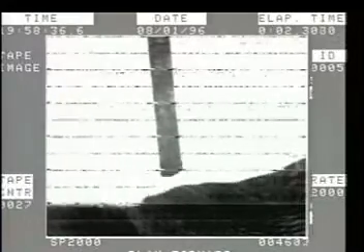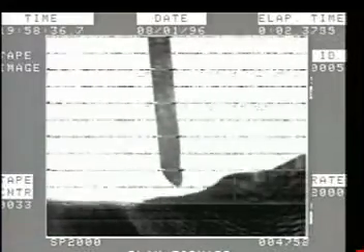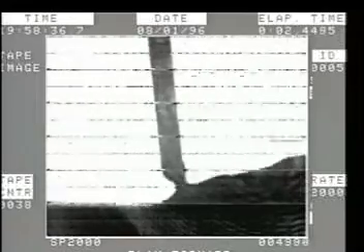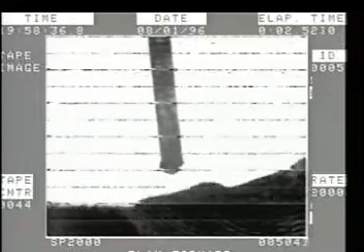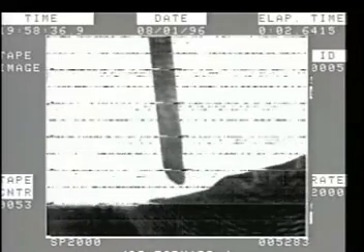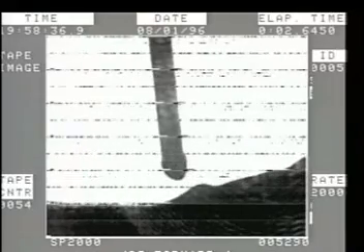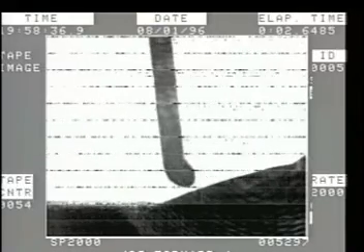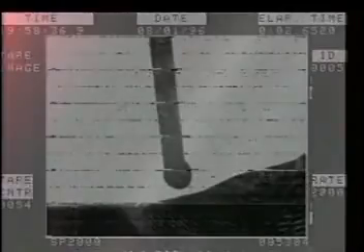Here is a close-up of the short-circuiting process. There's some spatter, a little bit of violence associated with the arc. The crisp buzzing sound is caused by periodic short circuits. By using high-speed photography, you can actually see droplets forming on the end of the electrode. Current is applied, the droplet is pinched off, and transferred into the puddle. Spatter occurs when the shorting is not done perfectly or there is interference to the puddle. Spatter balls can pop out of the very violent puddle as it oscillates.